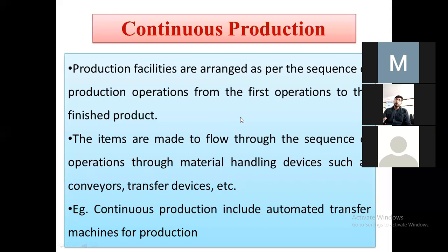Now you know the VMC machine. What is meant by sequencing is also important. In the VMC machine we are providing the codes. So after the turning, the drilling operation, after drilling the broaching operation, after that the milling operation. These operations are present in the program in a sequential manner.